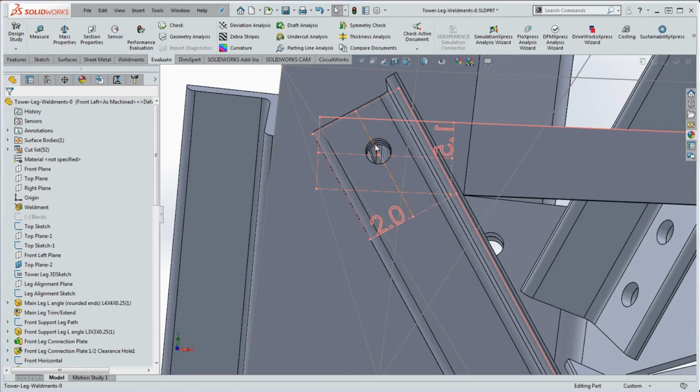And what that does is provide alignment points. So you can see alignment points in here. We have two of them. One on a 1.5-inch horizontal that exists in the background. That goes in first. Remember, there's history associated with this. And we're also stacking these too. So we have to get our main tower leg in here first, 1.5-inch horizontal in second, which has got a relationship with the 3D design sketch in the background.